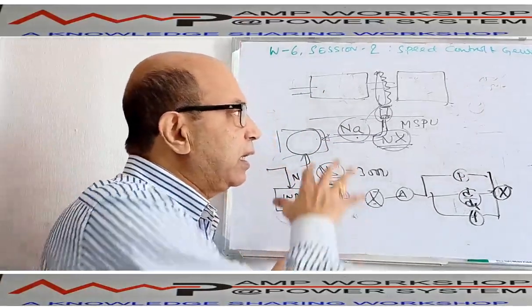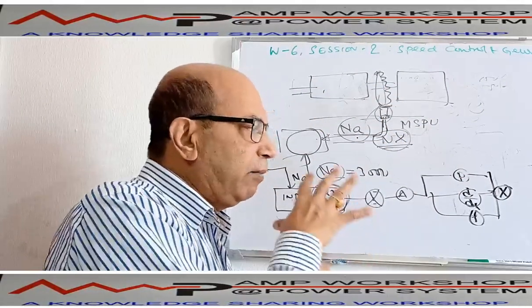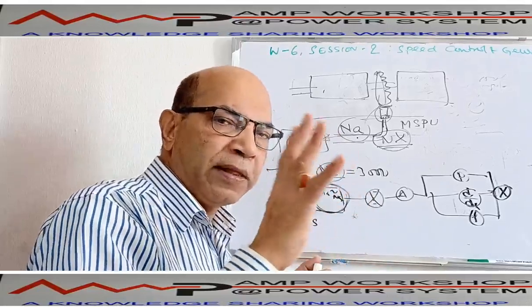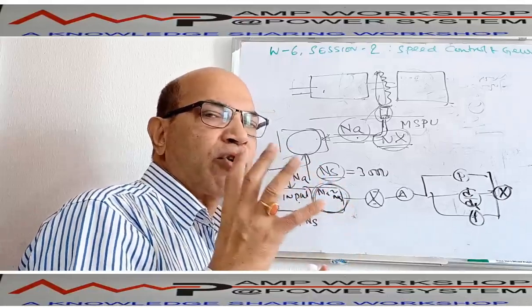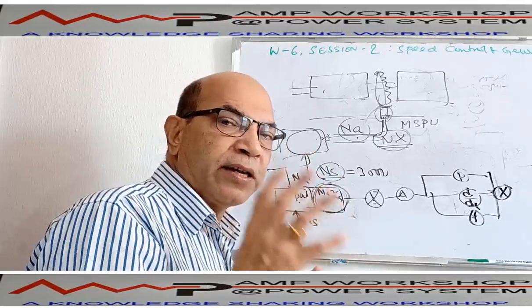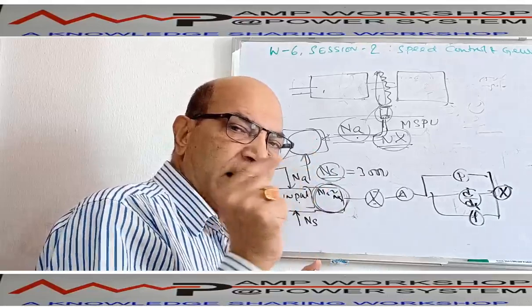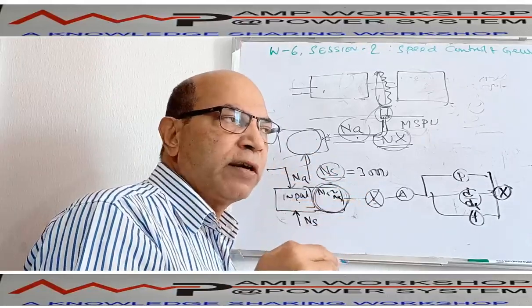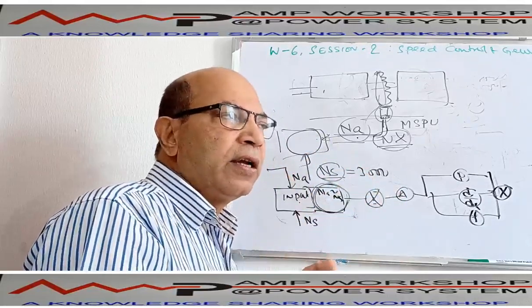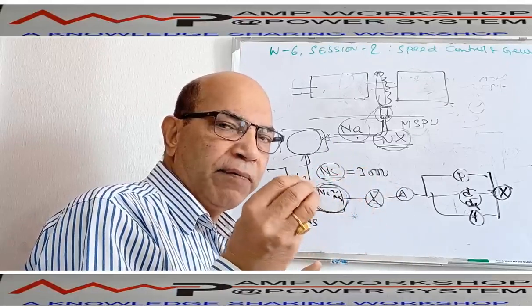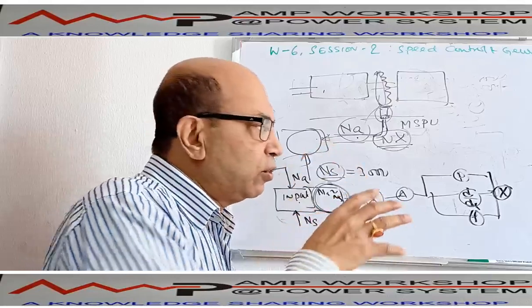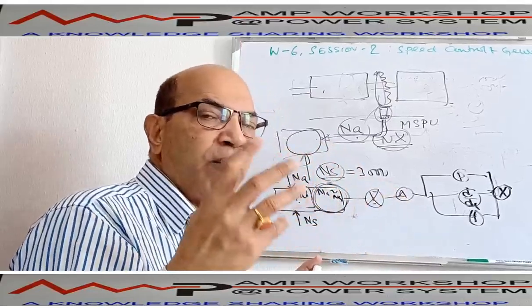In the case of a turbo generator set, ultimately the signal has to open the fuel valve. How is the fuel valve operating? The fuel valve is a motorized valve, MOV operated. There is an actuator, and the actuator takes the current and rotates. As you send more current, it will rotate more. It is a control valve, but a motor operated control valve. If you give less current, it will rotate less. So this needs an actuator, a motor, to be rotated.